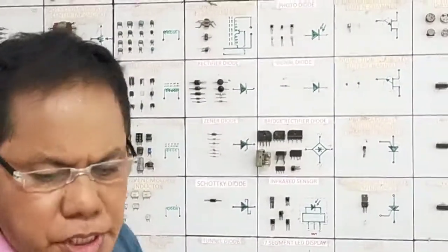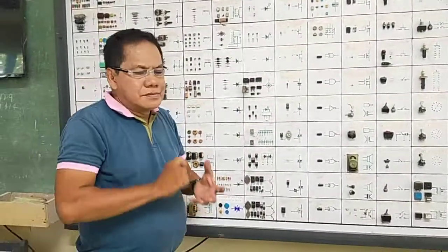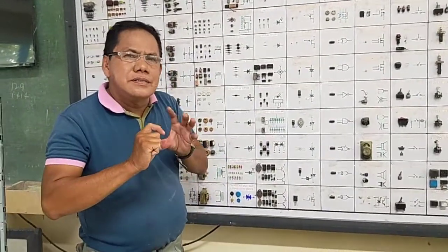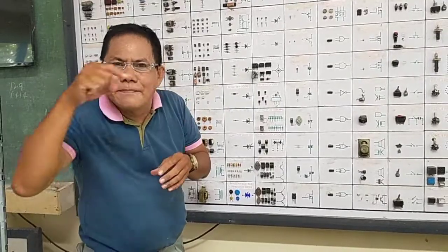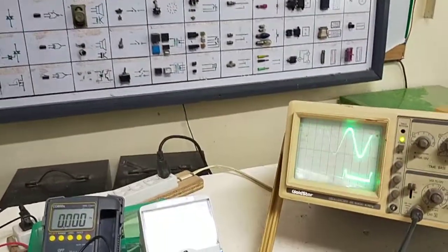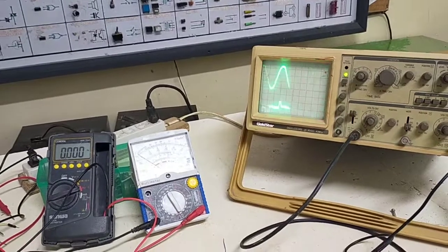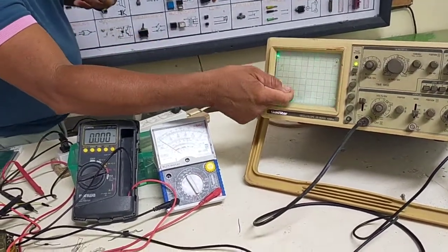The Zener diode is used as a voltage regulator. It actually eliminates pulsation. There is still varying voltage at the output of the supply filter capacitor. That will cause a little amount of hum because of that variation. There is still 1 to 2 volts variation.